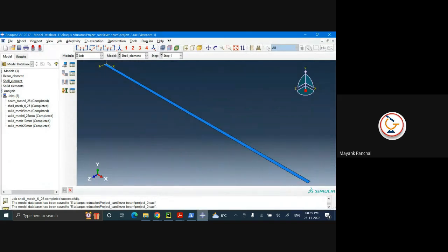Even if we had material non-linearity, say our loading is very small, so displacement is very small. When displacement is very small, you don't have much material non-linearity, and then you won't face any convergence issue. So there won't be any cutbacks. So standard will give you the solution very fast.